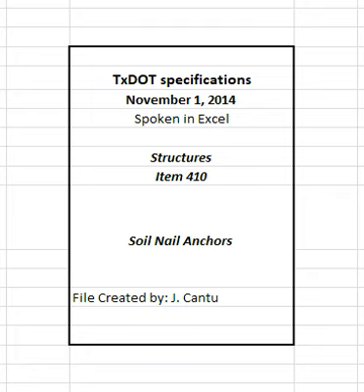The total measured movement at the maximum test load exceeds 80% of the theoretical elastic elongation of the unbonded length of the test nail. A pull-out limit state does not occur for the proof load listed on the plans. Pull-out limit state is defined at a load level at which the test load cannot be further increased while there is continued movement of the test nail. If the proof test nails fail, the contractor's engineer is responsible for redesigning the wall with supplemental soil nail anchors.